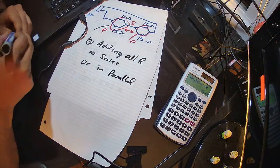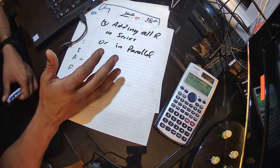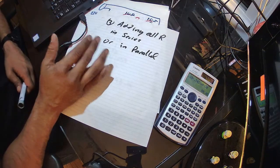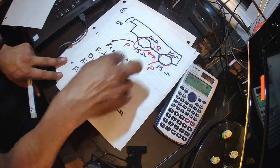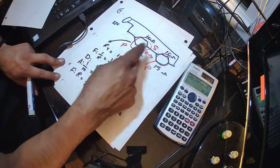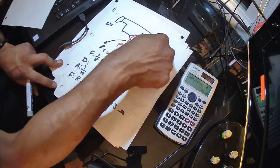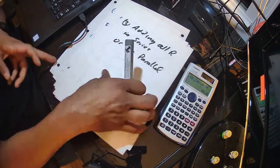So follow these tips. First thing you do is recognize what is in series and what is in parallel. Resolve the parallel circuit. Then reduce the circuit to make things a little bit easier for you so you can see them correctly. Like for here, we did this one by itself. Then you do the same steps for the other one and find the total for this resistance. I think this should make it a little bit clearer.